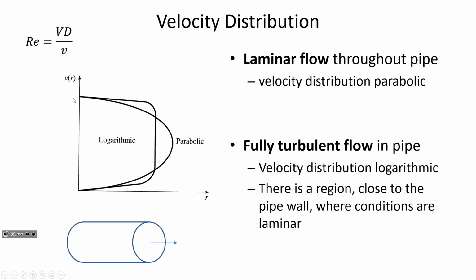But at the top of the pipe and the bottom of the pipe, really it's circular, of course. So if you think about this, it would be bullet shaped in the case of a parabolic profile. So try and think in 3 dimensions what that would look like. And of course, Reynolds number can be calculated with the velocity times the diameter divided by the kinematic viscosity. So we have different profiles depending on the flow conditions.